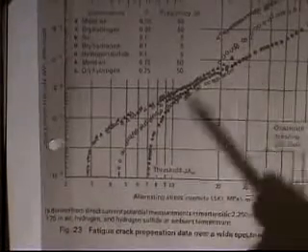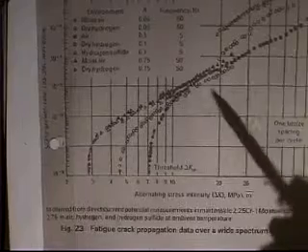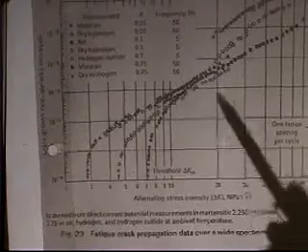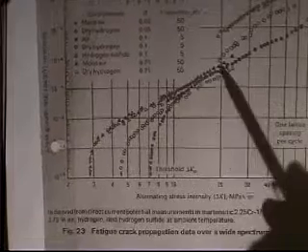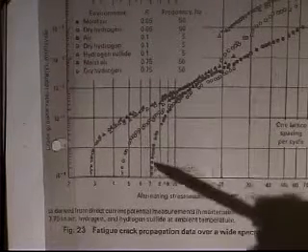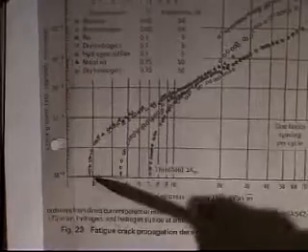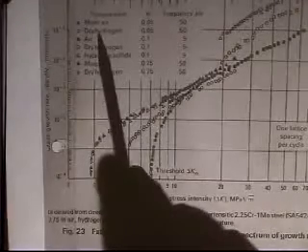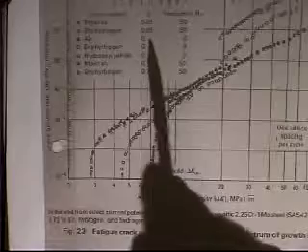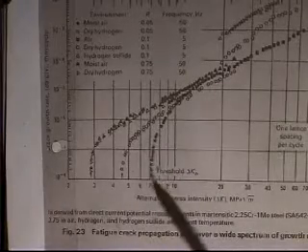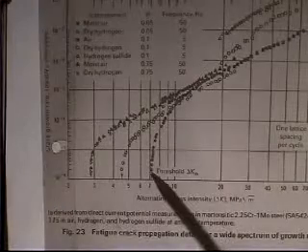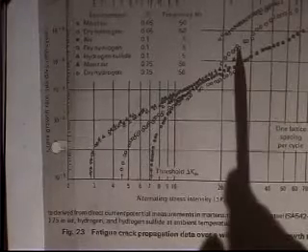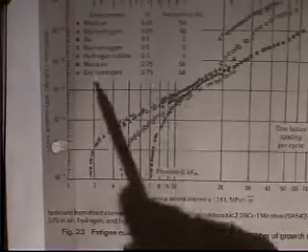But the slope here in stage 2 is always the same. In fact, they call this the Paris law because Paul Paris, now at Ohio State, was the first to articulate this linear region here. The threshold stress can change dramatically. The stress intensity can go from 3 to 7 depending on whether it's dry hydrogen or probably air. Which one is this? Moist air. This is moist air. Where's the hydrogen? Dry hydrogen's up there. Let's see, there's also dry hydrogen down here.